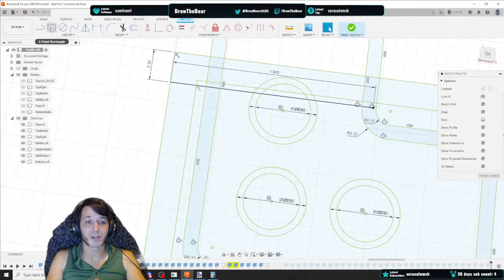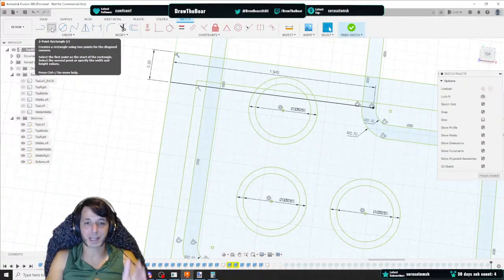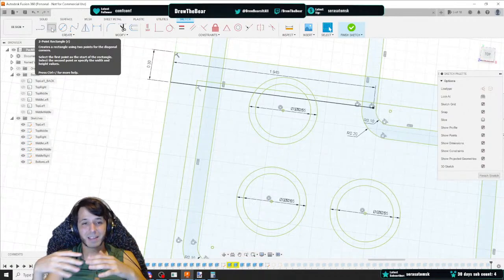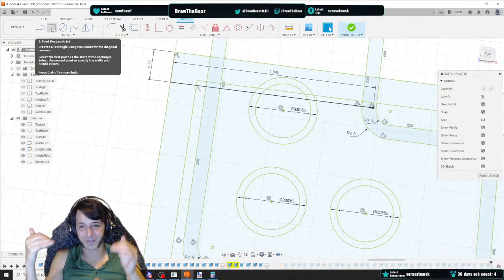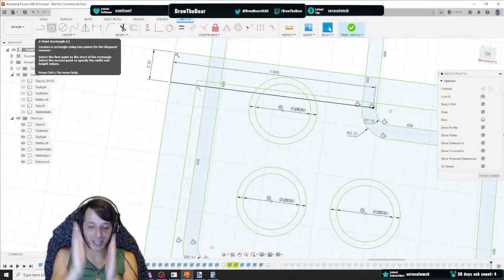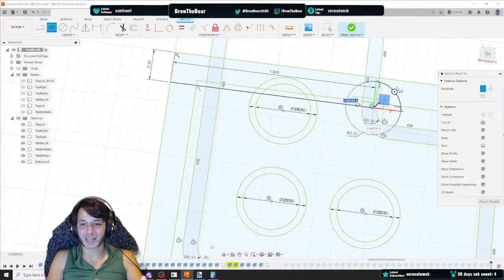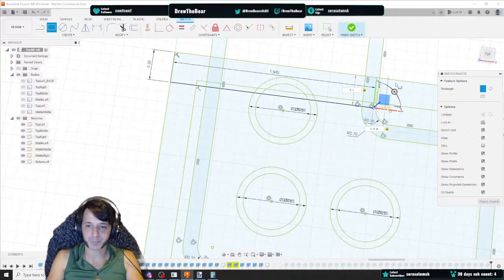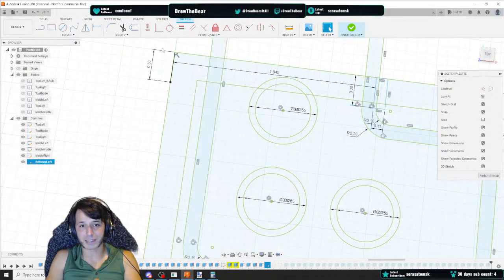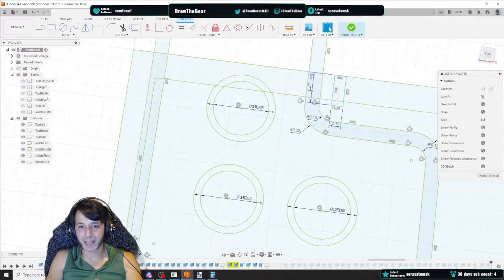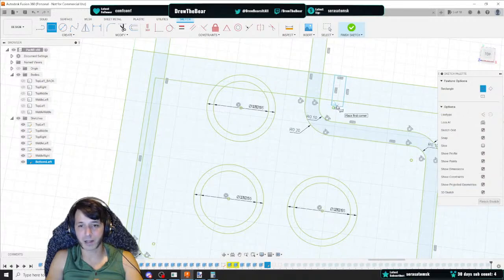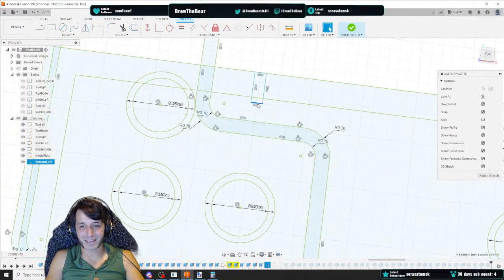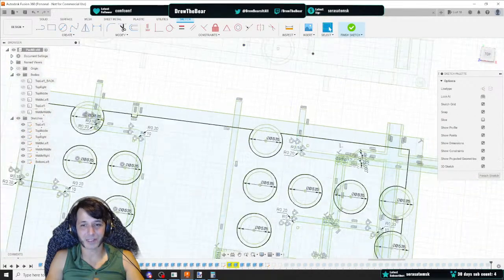Okay, so if I want to create a socket where the center of the socket is 2 inches from the side and the socket width is 0.11, then I have to create a line that is 1.945. That is the distance to the first side of the socket. I know that all seems like a lot, but if you look at it here, and I say 0.11 and 0.3, now I can delete these two lines easily. And what I have is a little socket I can create where the center point, if you look here, it locks and creates a little triangle, is 0.2 from the end. So this is now ready to go.